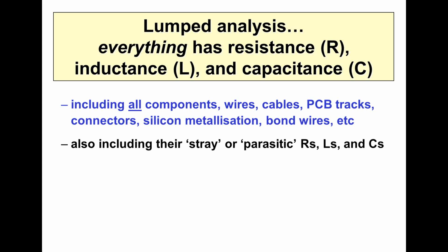It's quite interesting to work out what happens if you've got, say, a 100mm long trace on a fiberglass printed circuit board that's bolted to a piece of metal. There's quite a significant capacitance there, and it modifies the resonant frequency of that trace. So you can find that just by moving a trace or a PCB closer to or further away from a sheet of metal, you can tune the frequencies at which you have problem emissions.